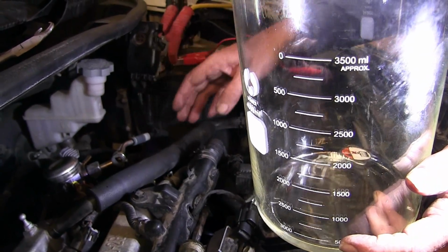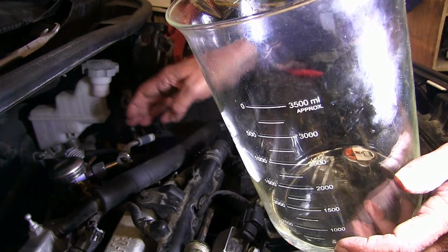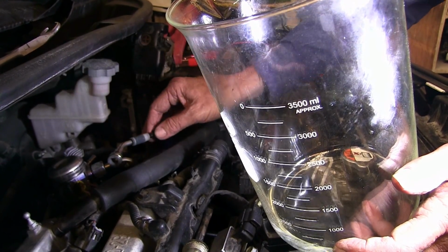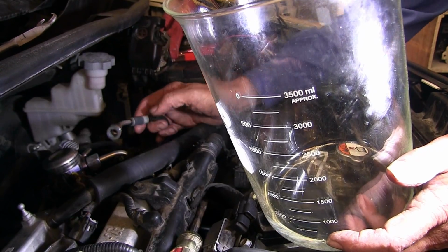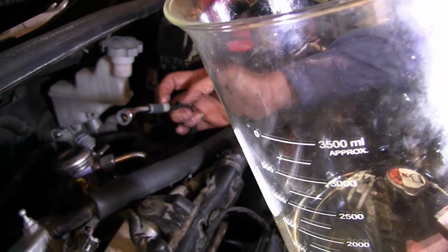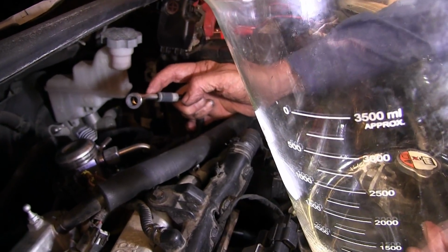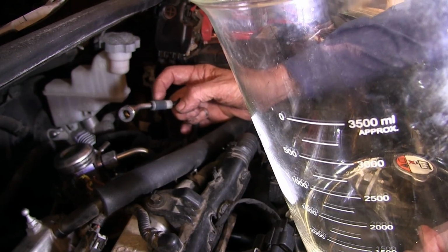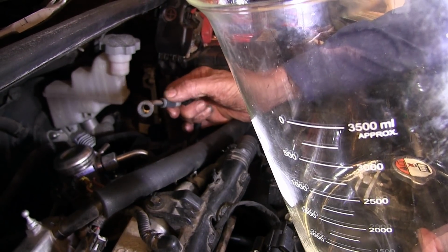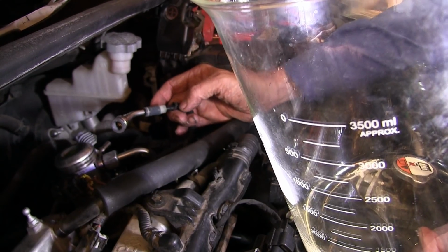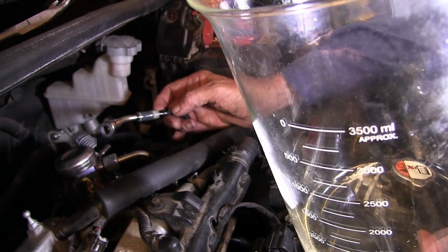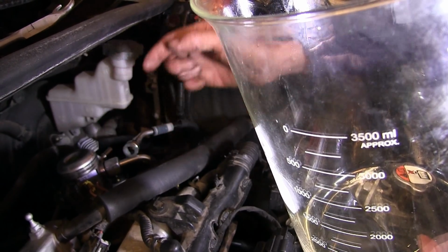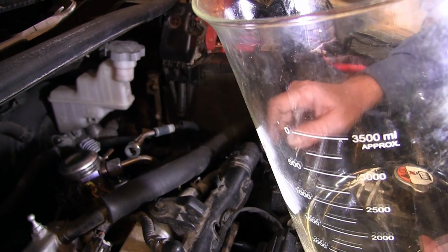Now, I've raised it up on the lift and I pulled all the plastic covers off underneath the car that covers this line. This line is good all the way back. The only thing I can see is I don't think this is stock. I think somebody put a connector fit in here and this is a fix. I think this is where my restriction is, but I'm not sure. But the one thing we're positive of is it's good out of the pump module and it's bad out of this line. Somewhere in this line there's a restriction.